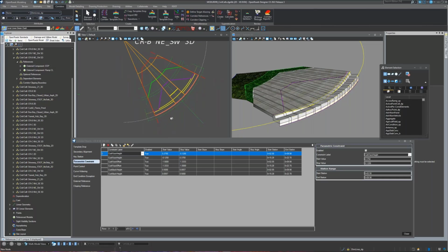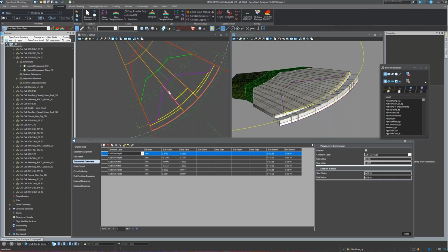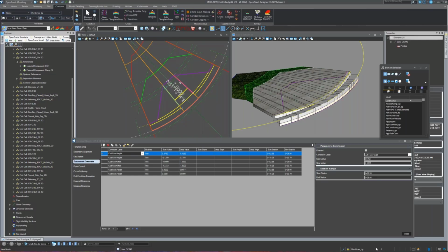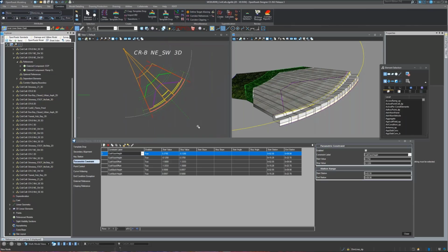And that's going to be completely dependent on the profile of your curb return as well. So if your curb return's doing some weird things and it's really steep, or it's got a curve on it or whatever it is, you want to be able to evaluate, is this 7 feet long enough for my curb ramp to come down at a 1/12 or flatter? And so I would just need to come put some profiles on here and check that.